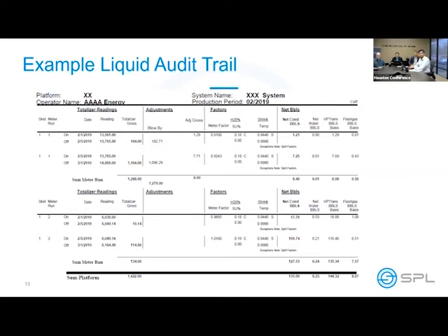We calculate, for example, a transportation barrel. A lot of times in the gathering systems, they charge transportation based on a high pressure barrel, and that simply is corrected and the shrink backed out of it, if you will, in order to calculate how much it is as a high pressure liquid. And then of course, flash gas basis, in this case, is barrels lost to shrink. That's the amount of barrels lost to the shrinkage factor. A lot of times we will use that to allocate flash gas in a given system.